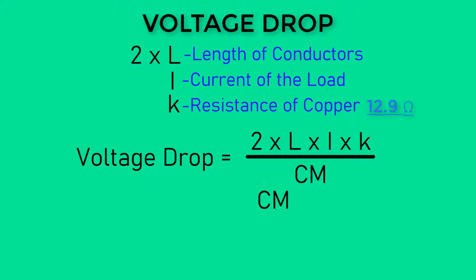The size of the wire supplying the load must be identified since different conductor sizes affect the voltage drop. The completed formula results in the total voltage dropped in the conductors. The voltage dropped in the conductors is subtracted from the voltage source to solve for the load voltage.